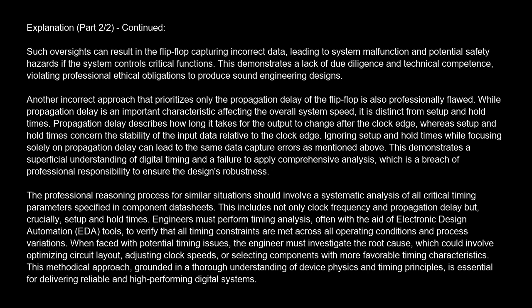Another incorrect approach that prioritizes only the propagation delay of the flip-flop is also professionally flawed. While propagation delay is an important characteristic affecting the overall system speed, it is distinct from setup and hold times. Propagation delay describes how long it takes for the output to change after the clock edge, whereas setup and hold times concern the stability of the input data relative to the clock edge.